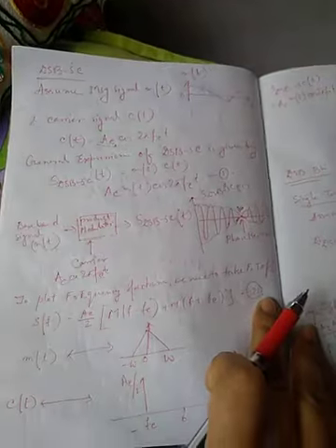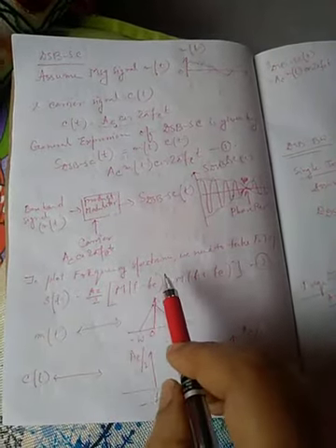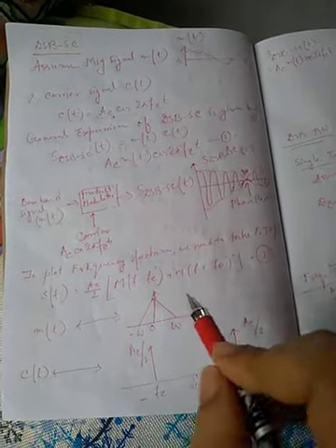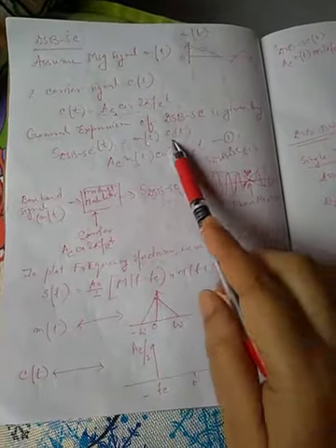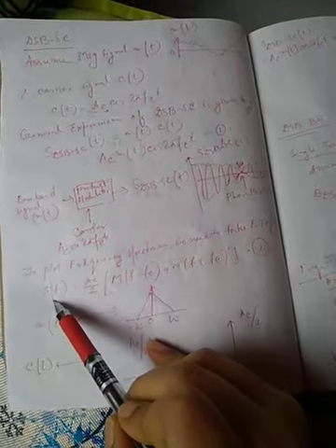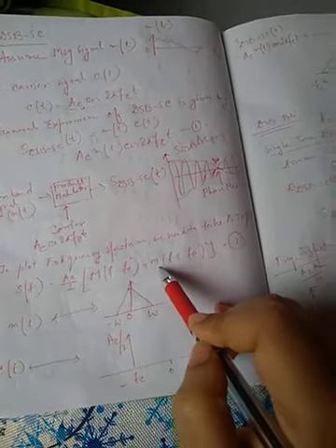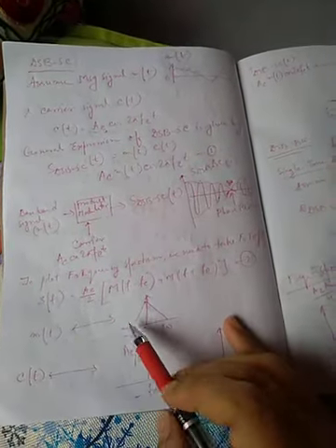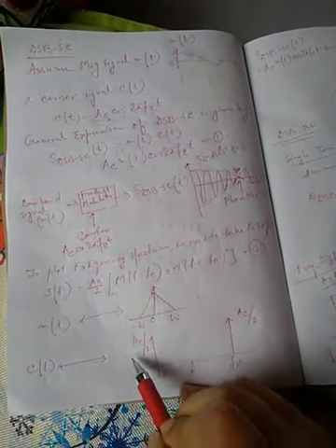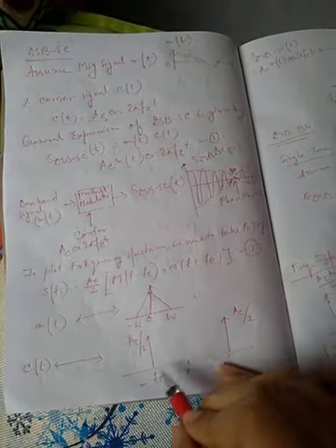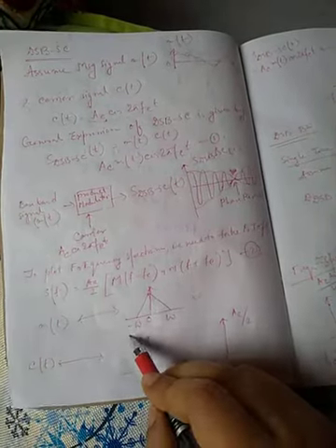Now let's come to the spectrum of the double sideband suppressed carrier. To plot a frequency spectrum, we have already discussed that we take the Fourier transform of the entire signal. Taking the Fourier transform of this signal gives S(f), written as Ac/2 [M(f minus fc) plus M(f plus fc)]. Here I have drawn the message signal frequency spectrum this way. Next, the carrier signal frequency spectrum has two parts, fc and minus fc. The message signal has two frequency parts, plus omega m and minus omega m.